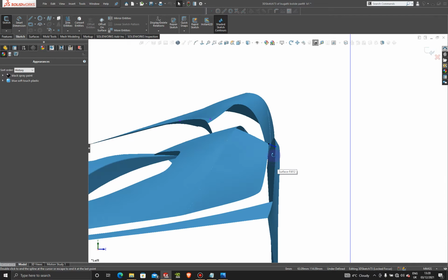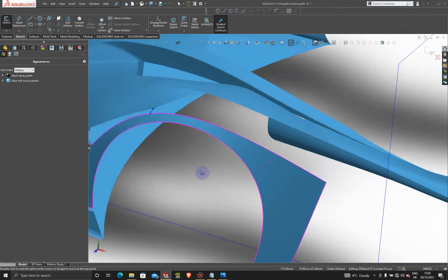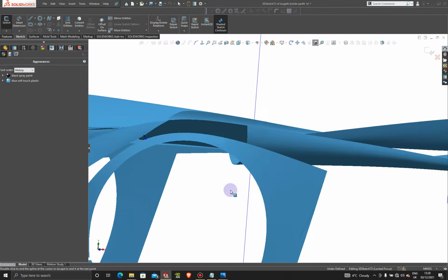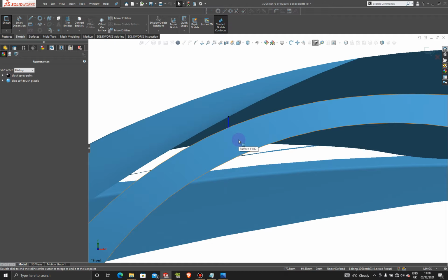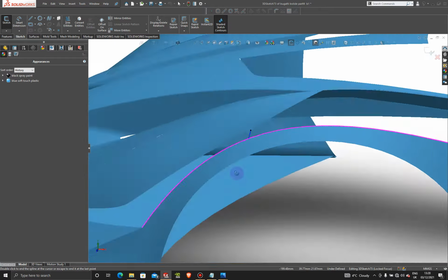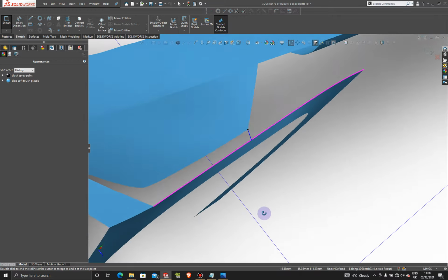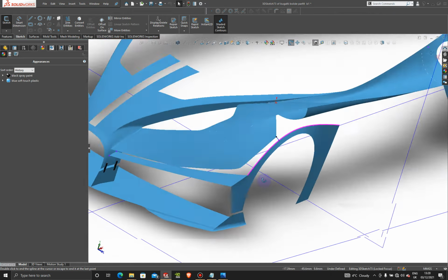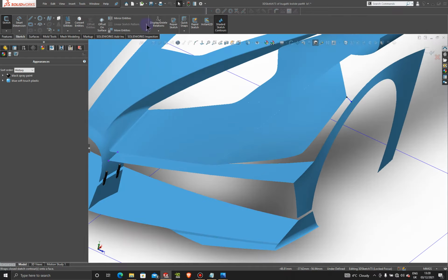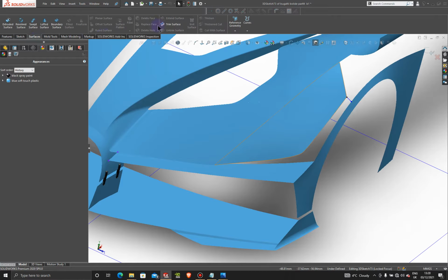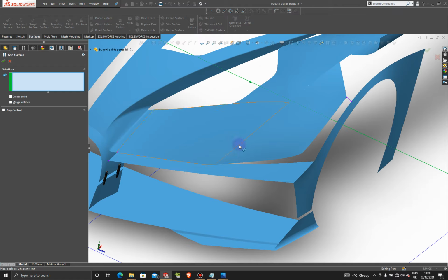We're not going to add any profile on that one, but let's have a look at the small cutoff from the side. Look, that looks straight enough. All right, good. Next thing we're going to do is go to surfaces and exit this small 3D sketch from there, and we're going to knit together these two surfaces here.